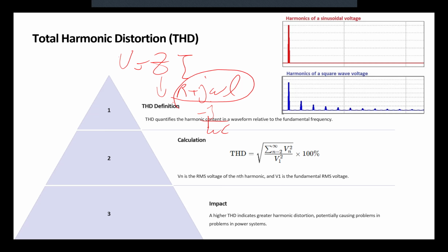If I have harmonics in my system, those high frequency harmonics see higher impedance, because omega is higher. So at 60 hertz we have Z1, but at 180, because the frequency changes, we have another Z. Remember the rule: when you want to analyze a system, one frequency at a time. You cannot mix frequencies in AC circuit rules.